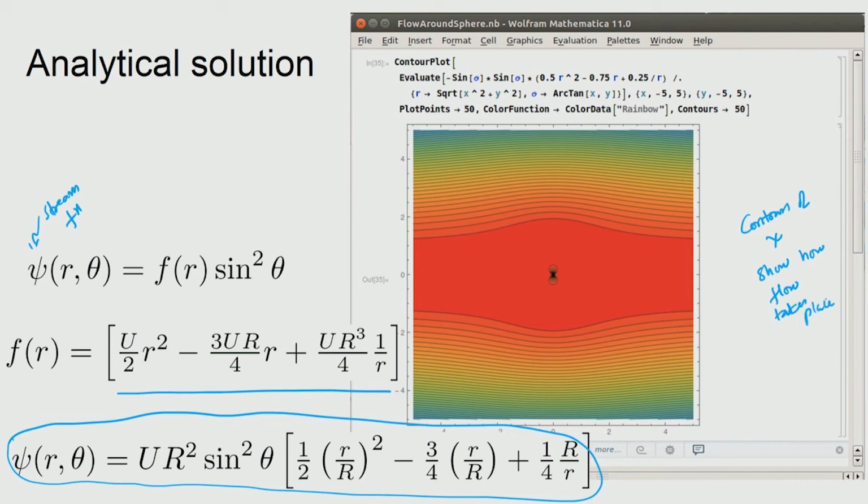So, what we have done here is a small one-line MATLAB script to show you. You can see that we have this function, which is nothing but the f of r, and then we convert the coordinate system from polar to xy and plot them in a range.